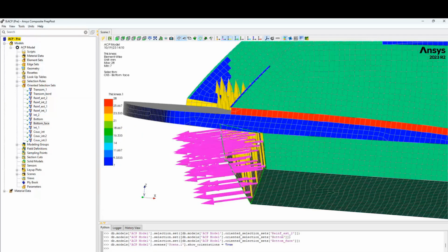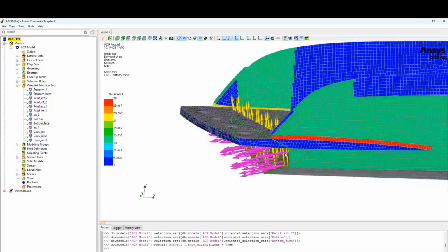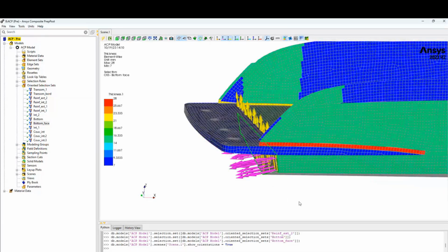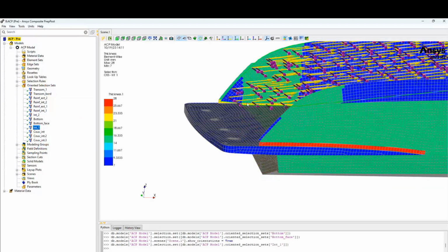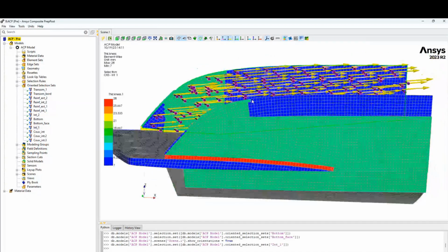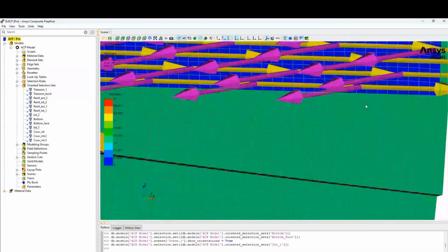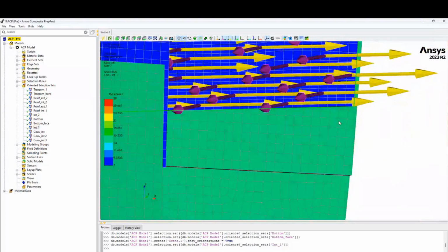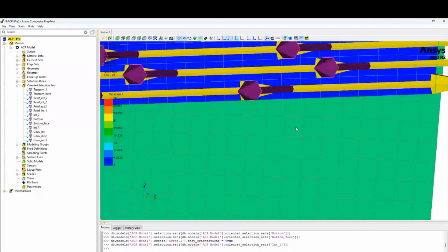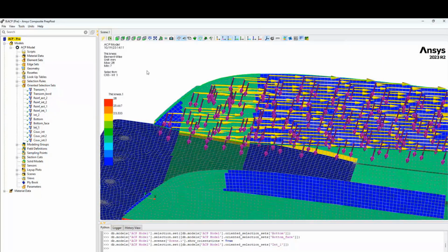For example, we can add the layers to the outside or to the inside of the boat. In this case, I defined it in that way in order to add all the plies to the exterior. We do the same thing for each zone. For example, here we can see our reference vector is not horizontal, it is defined following the edge of the blue geometry. We can see that here. And that's the way we construct this kind of parts.